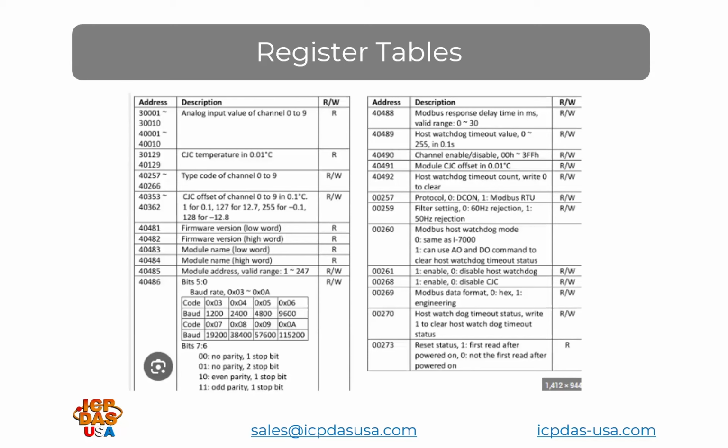The slave devices will have a defined table like this, which defines memory locations where the corresponding data is stored. Some of these data are read only. These are your discrete inputs and analog sensors, while other data is readable and writable, like DO and AO values.